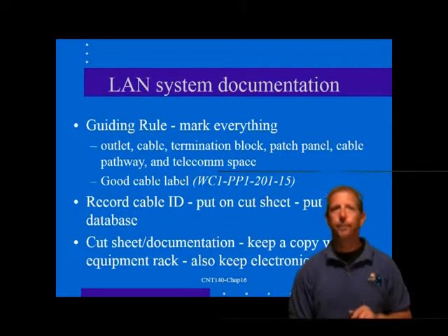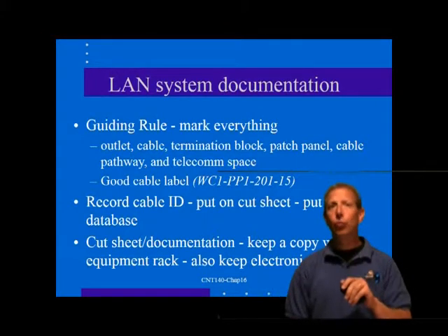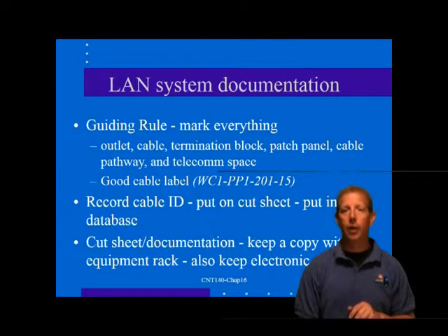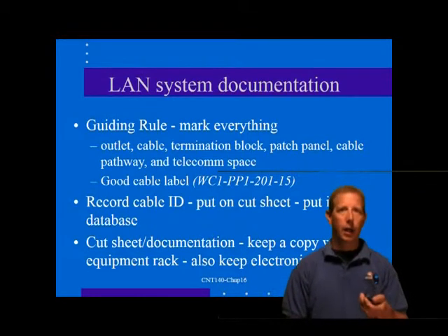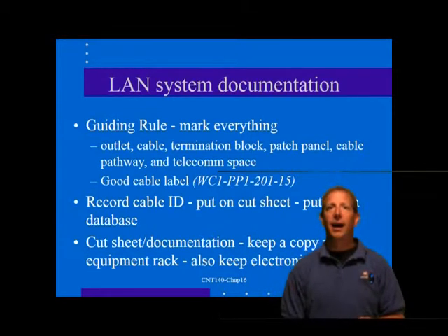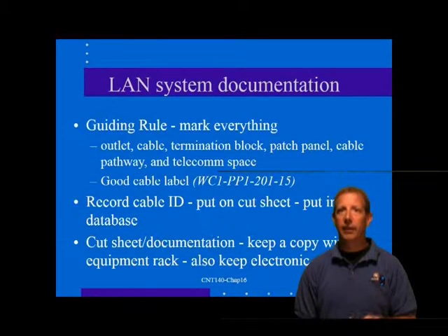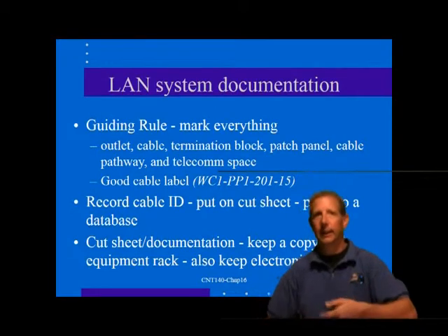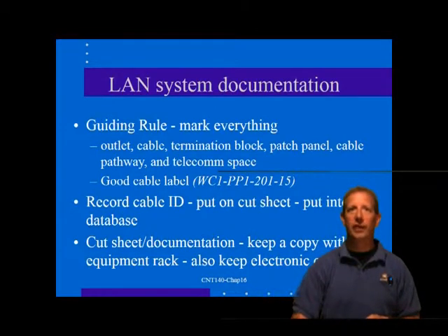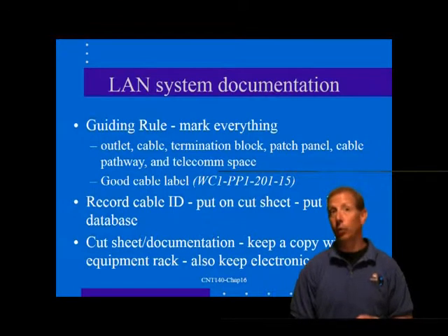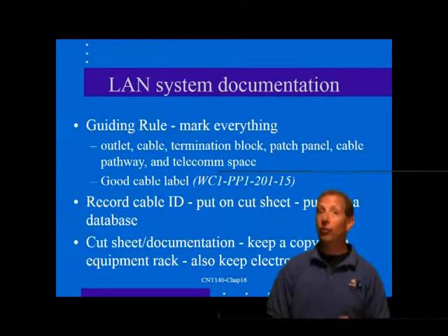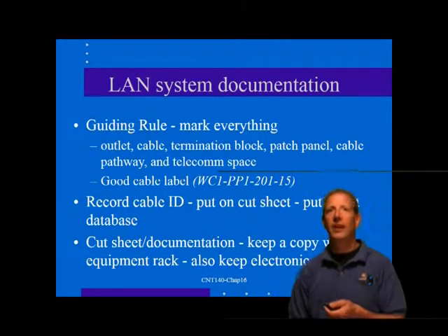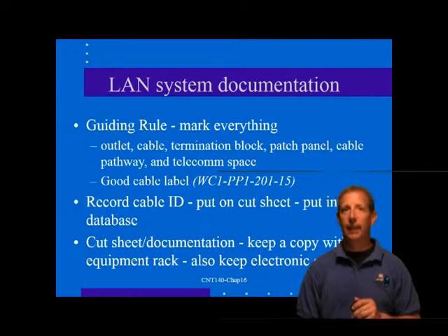Now, the guiding rule for a proper LAN documentation system is mark everything. That is, systematically identify every outlet, cable, termination block, patch panel, cable pathway, telecommunications space. Then record those identifications on drawings and database for quick reference. If you do not carefully manage your LAN wiring installation, the constant pace of changes to the system will soon disorganize things so much that you'll be forever lost in the cabling maze.